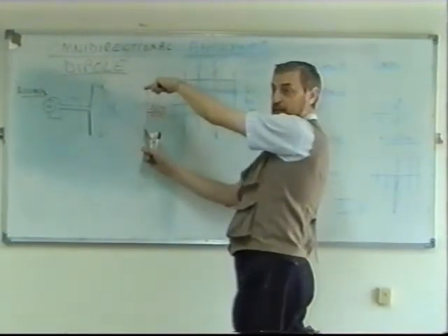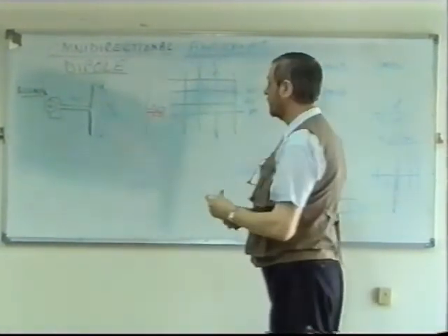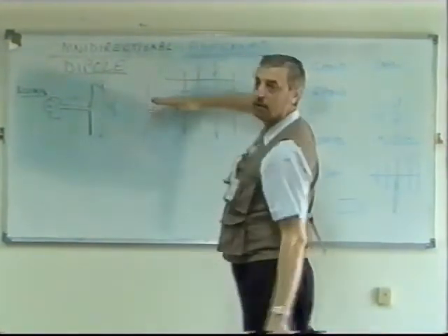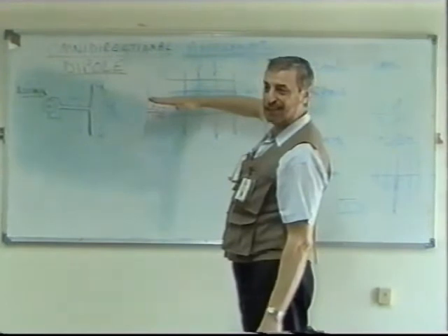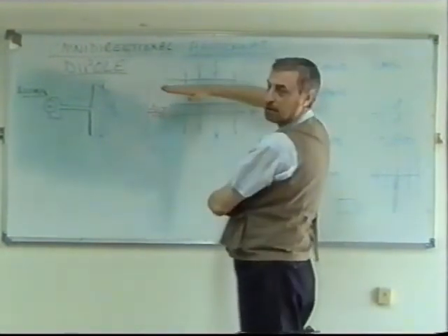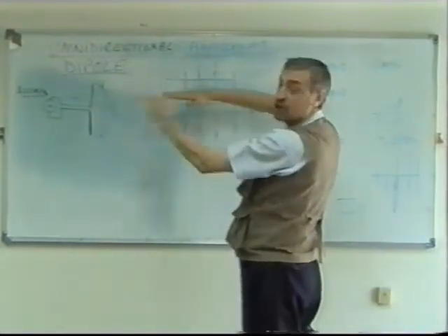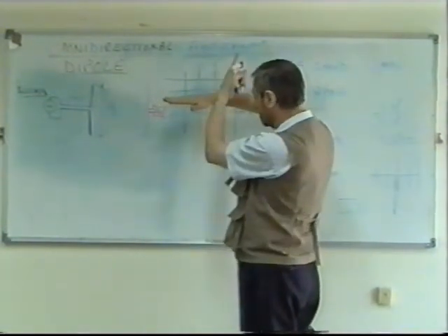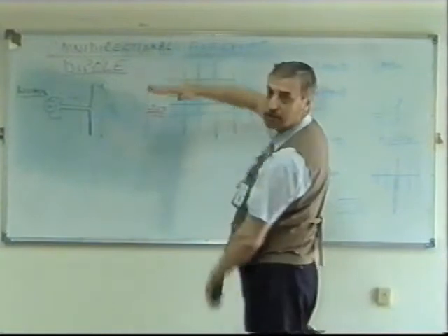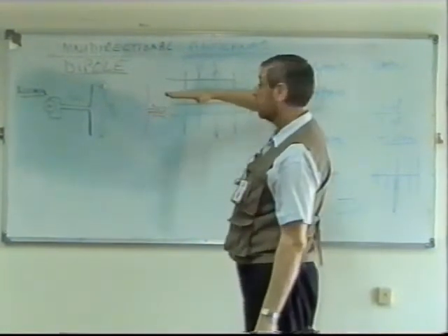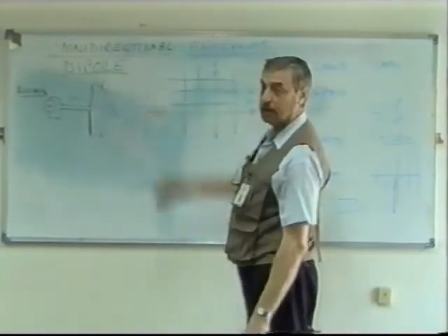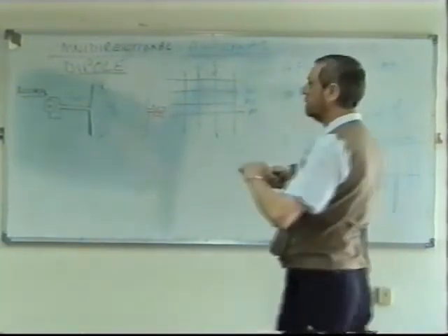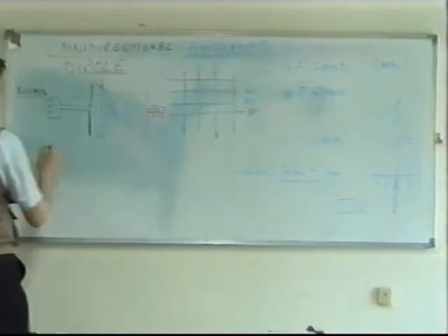the transmitter antenna. If I didn't do that, if I put the antenna this way, I will not receive the signal properly, because the electric field is not going to induce a voltage in the length of the antenna, and the magnetic field is not cutting. The magnetic field's got to cut it at right angles, and it isn't going to do that. So if I put my antenna that way, I would, in theory, receive nothing. We call this polarization, and it's an important point.